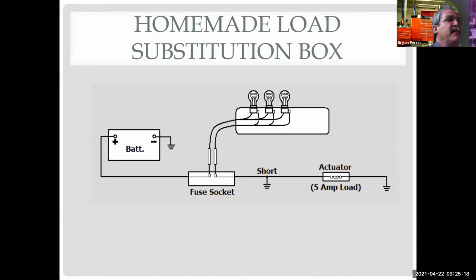So I've made a couple of these over the years. This one's nice because it has the 6 light bulbs in it. I've also made one with just 1 light bulb in it and a buzzer. It was an air brake warning light buzzer, a light with a buzzer on it. We use them on semi trucks, anything with air brakes. I put that into a kit box with a power and ground. That was nice because I didn't have to see it. I could hook it up and hear the buzzing on something underneath the hood or underneath the dash, and I could work in the trunk and still hear that. Now, it drove my coworkers nuts, and I wouldn't want to use it every time if I can see the bulbs. But that's another way of doing it. So there's lots of ways to get there.